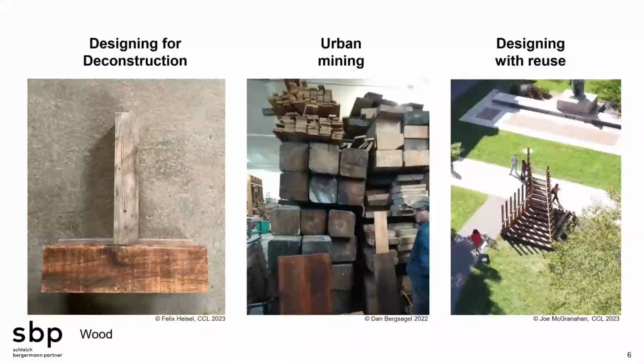So we did some work comparing how screws and connections perform in terms of strength and stiffness if the screws are removed and reinstalled in different methods. I think there are good opportunities there for designing for deconstruction even if the codes and design requirements maybe lag a little bit.